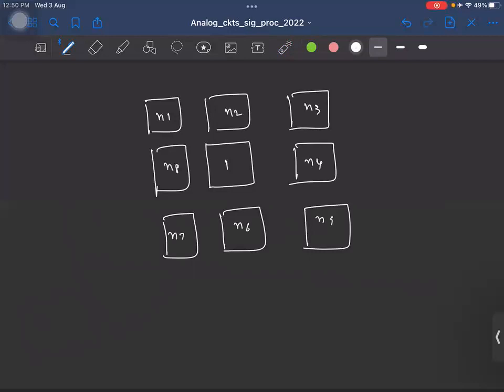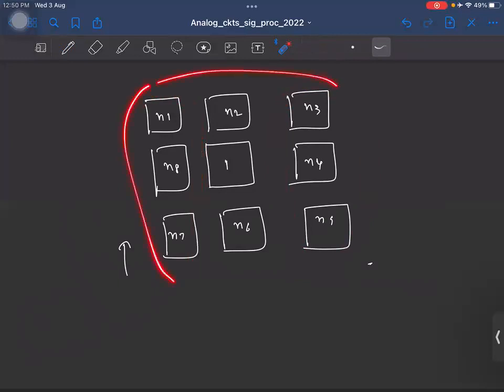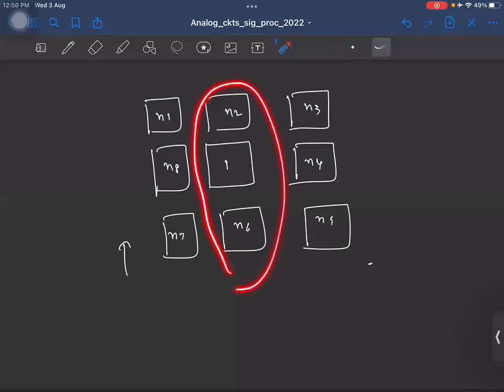Now let us say there is some gradient, like it can be temperature or any kind of gradient. So let us say this portion has a higher temperature compared to this. Now you see that the diodes on this side will have a higher temperature than the average. This will have a lower temperature. So on an average, you see the temperature will match the ones at the center.